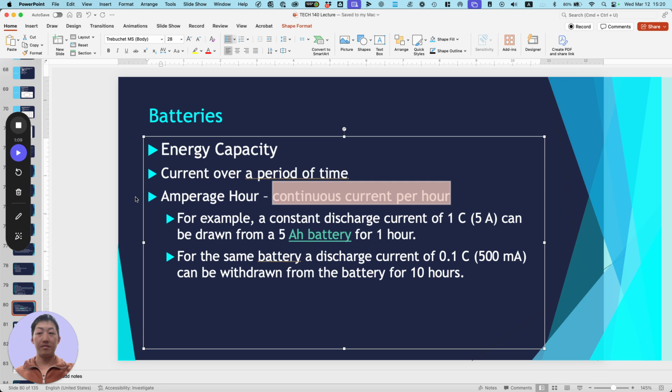All right, who needs help? I can help him too. Yeah, the two of us can go in. So we actually have a hex driver in your toolkit, but it doesn't have a deep enough pocket for the length of the shaft. I'll show you how we're gonna tighten this. We don't want to use pliers on this one, just because it's plastic, so it's gonna eat away. We're just gonna hold it by hand and, just like on the other end, use the driver and tighten it up. That'll be good enough for what we're doing here.